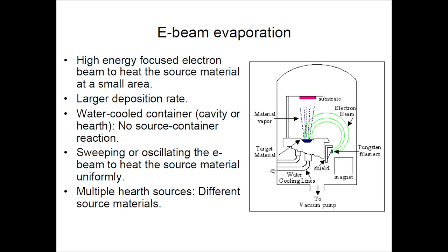Okay, so here also we need to create the vacuum inside the chamber, and further we will be heating this target material using the electron beams, and the atoms coming out as vapor will be deposited on the substrate placed above. And here you can see we placed a magnet. This magnet is placed in order to confine the electrons coming from the tungsten filament to a circular path.